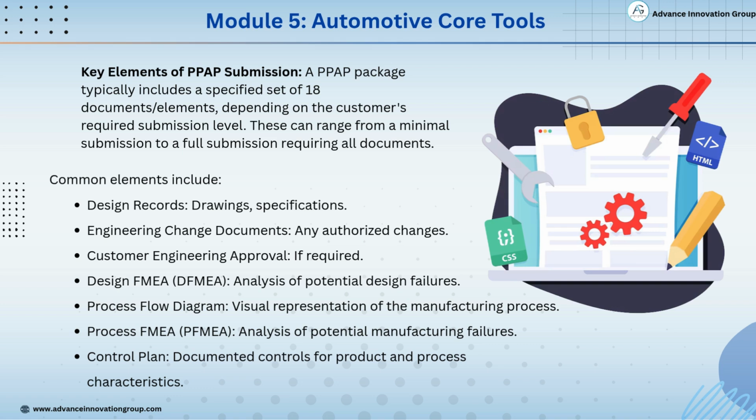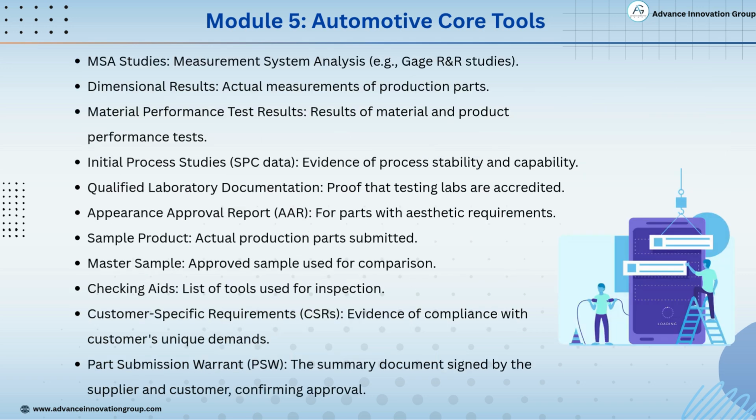Control plan ensures proper controls are in place for quality and consistency. Each document plays a role in proving the process is capable, controlled, and ready for production. These are the final documents that complete a PPAP package.